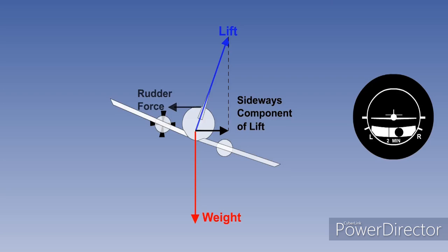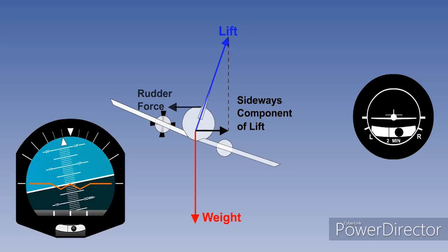The bank angle must be restricted to 5 degrees to prevent significant reduction of the vertical lift component. Banking towards the live engine also reduces the side force on the fin from side slip, which effectively reduces the yawing moment and gives more rudder authority to stop the yaw. The cockpit indications on the turn coordinator will be no turn, but the ball will be out to the right. This is the corollary of the indication in the wings level method, there being no side slip, but the ball is not central.